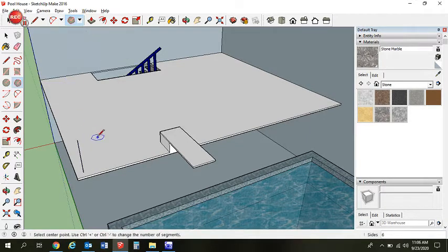So I'm going to go with polygon. It's asking me down in the right corner here how many sides. So I'm going to go with 3. Enter. You see it makes a triangle then. And then I'm going to drag that out. My radius being, let's go with 2.5 inches. Enter. Now this is the trickier part.